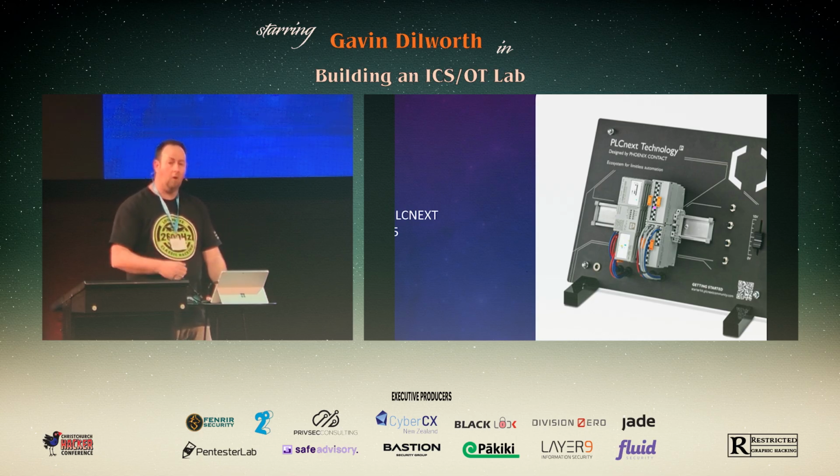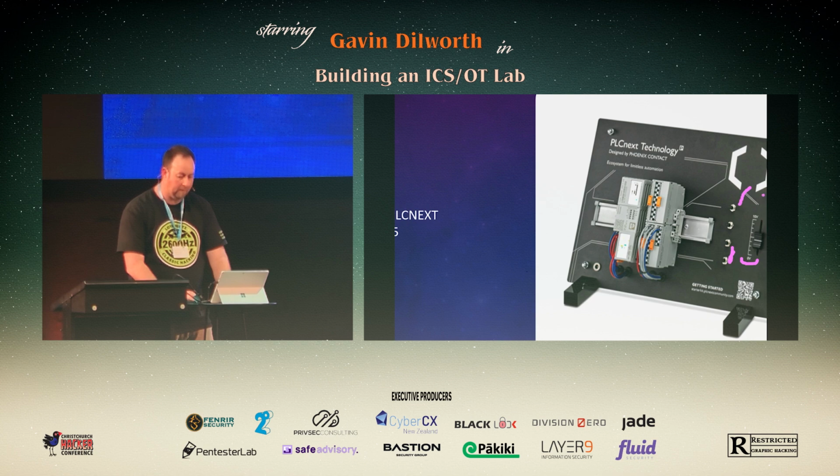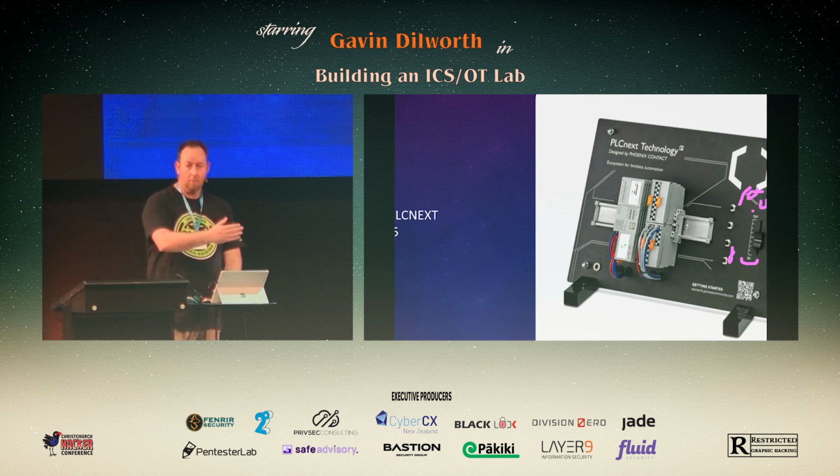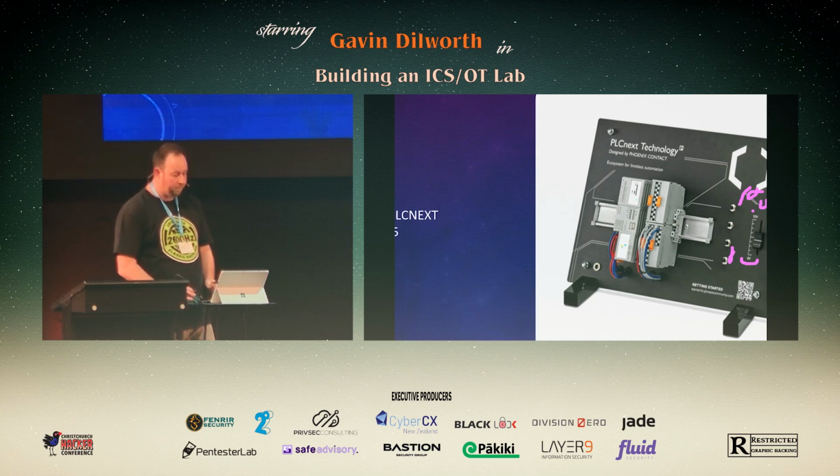And then you have analog with the values, like I was talking about there. 0 volts to 10 volts, that's basically a representative number. So it's an analog value. And once again, you have analog inputs, like how hot is this thing, and then an analog output, like how fast do you want it to now go. Okay, all standard in process control.